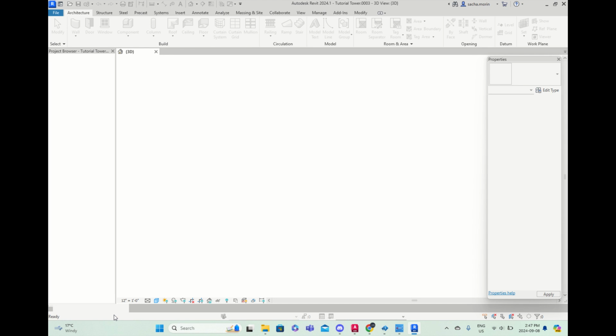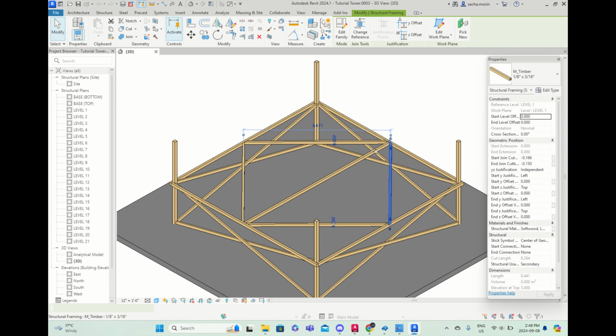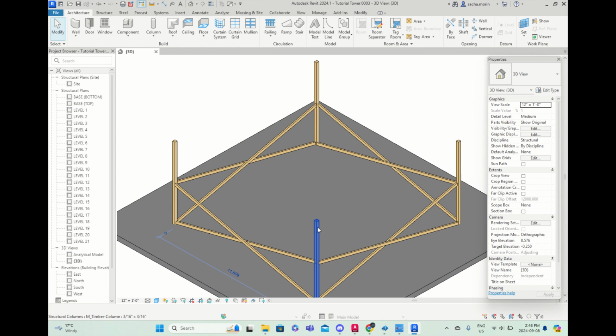But if you realize that the file you're trying to insert into another isn't inserting, that is because you have it saved as the wrong type of file. Only one of those, model or project, actually works for inserting, and if memory serves me right, the one that works is project. It's not something you'll ever see, hopefully, and not something I'll show you, but definitely a little nugget of information that might help.